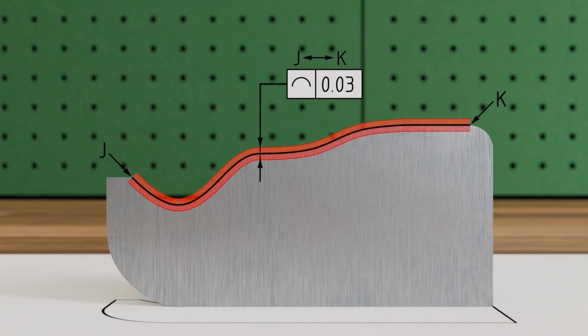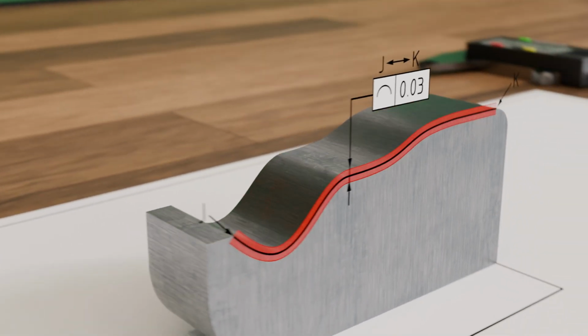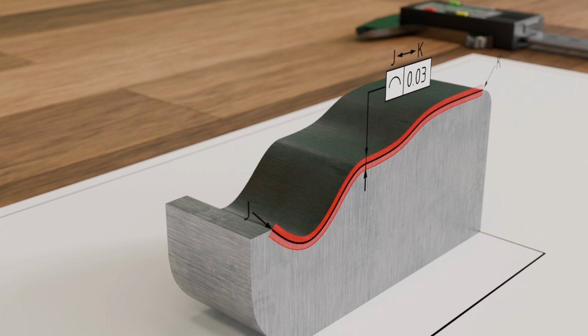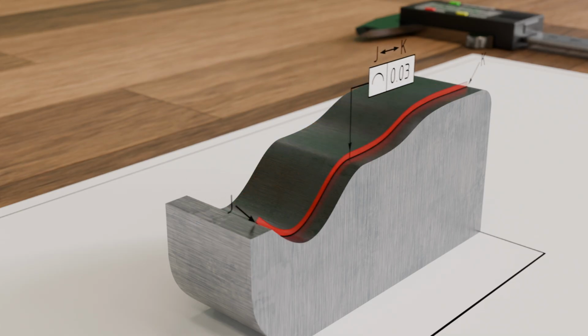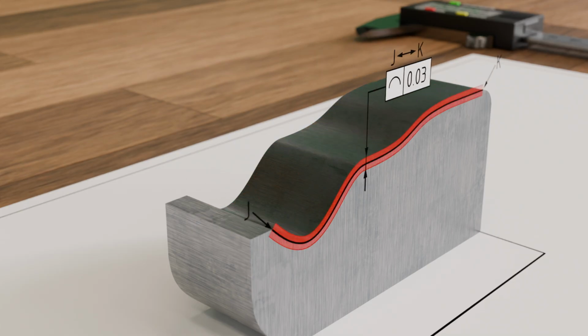Instead of the thin sheet metal, a thicker component with corresponding depth is now considered. Compliance with the tolerance zone must then be ensured in every cross-sectional plane parallel to the surface. To do this, we can mentally move through the tolerance zone perpendicular to the surface. It must then be checked whether the actual line profile of the surface lies within the tolerance zone.